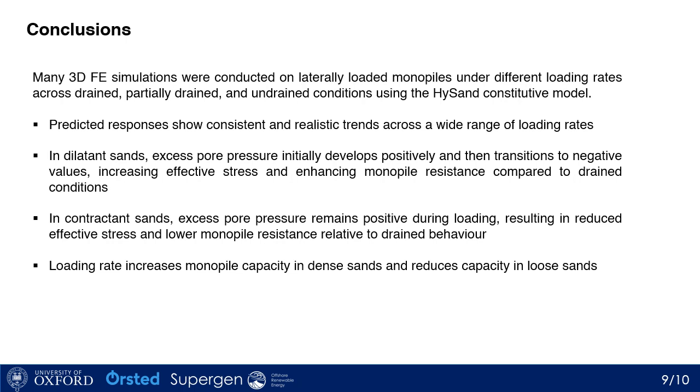The story is different for loose sand with contractant behavior because excess pore pressure remains positive during the loading, which reduces effective stress and results in reduction in monopile resistance relative to drained behavior. And overall, loading rate increases monopile capacity in dense sand and reduces capacity in loose sand.